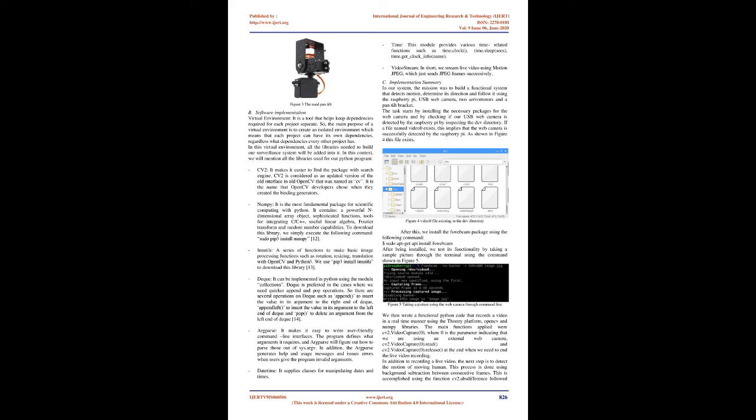Figure 1, overall behavior of the system. Figure 2, detailed behavior of the system. The user of our system can surveil and cover the whole motion happening through the usage of a single camera. The process starts by launching the camera and capturing frames. These frames are processed in order to detect and localize motion. This is done by performing frame subtraction between a reference frame and the current frame. If motion is detected, its direction is calculated, and the camera is moved toward this direction in order to keep track of the moving human or object.